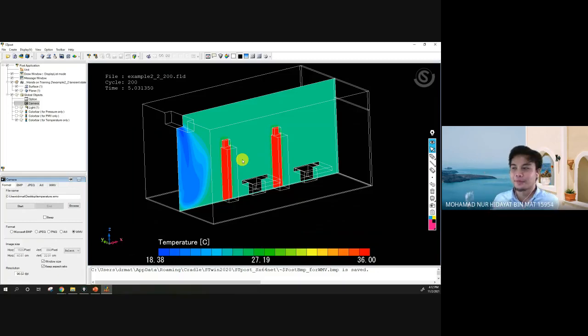That is why you need to investigate. I myself do not know because I never did that. So you need to create the ceiling aircon having a specific flow rate, and then you do the transient simulation analysis, and then you can see what is the thermal sensation of the human.